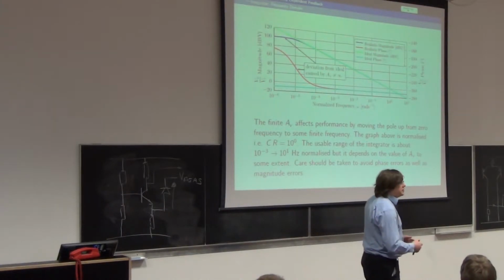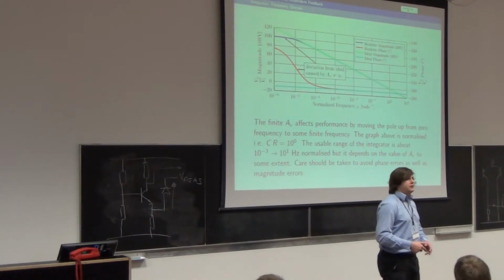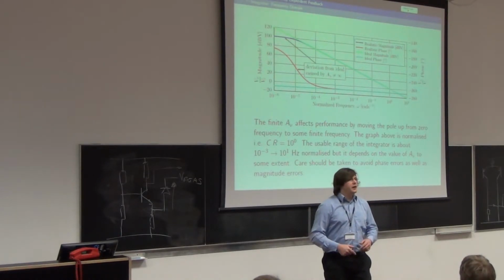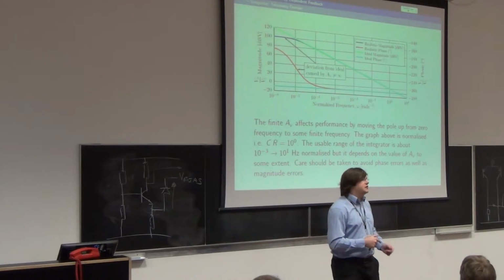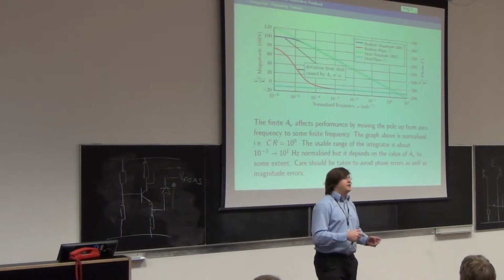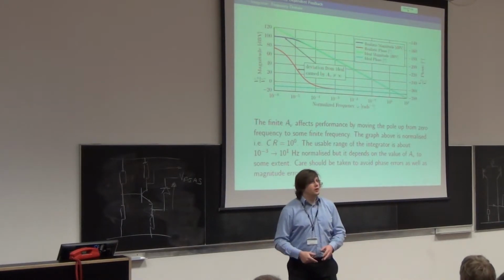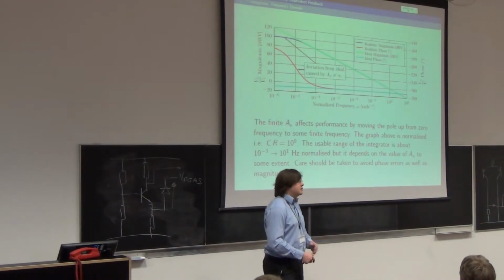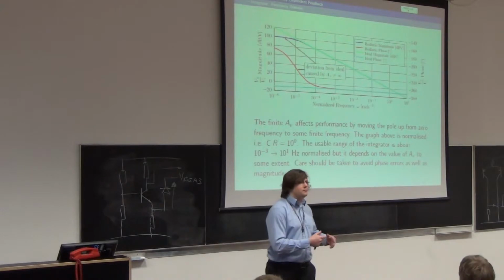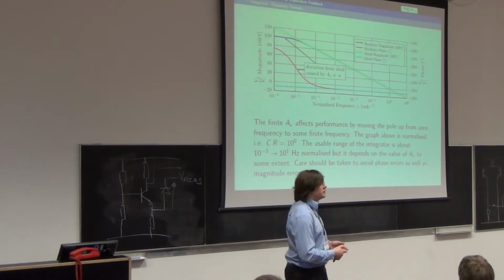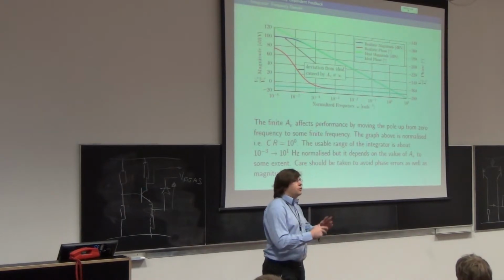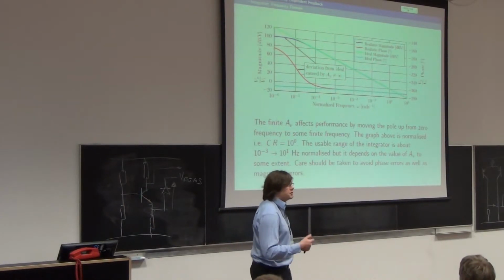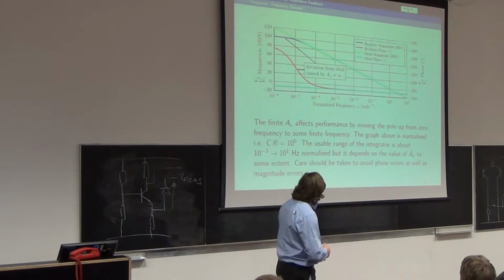On the other hand, since you know that you're going to make those assumptions about your op-amp, you may as well just dispense with all that simulation, write out your op-amp equation, and remember that your simulation isn't going to be perfect. And if you want to figure out how it's not going to be perfect, then you can go and do the difficult simulations later. So the first time you start to figure out circuit design, usually make all your assumptions and see what happens in a perfect world, and then you can start worrying about everything else afterwards.